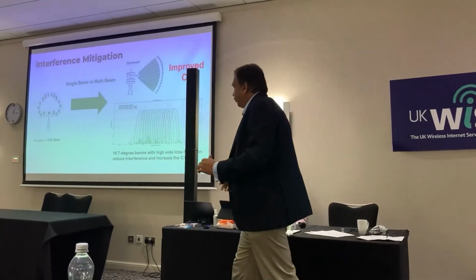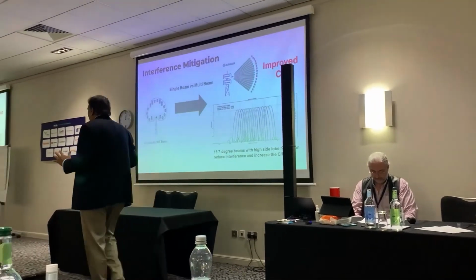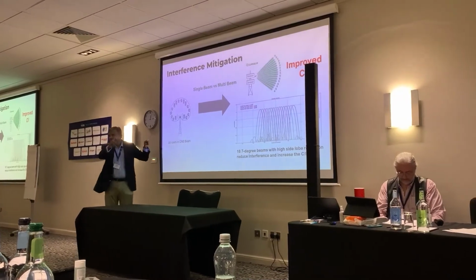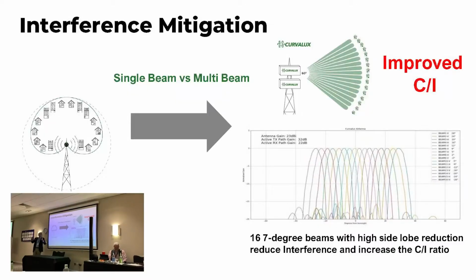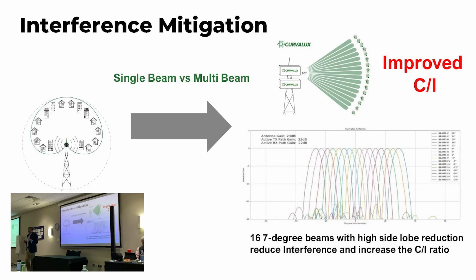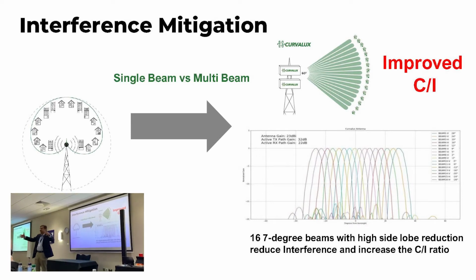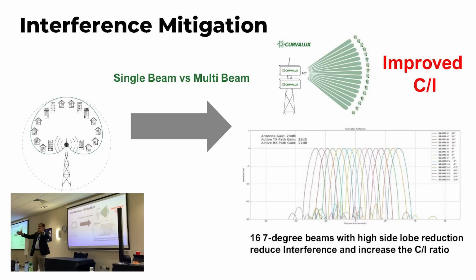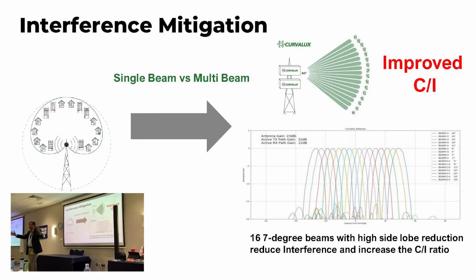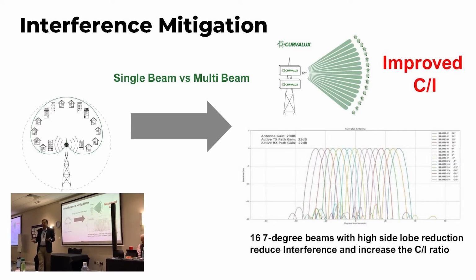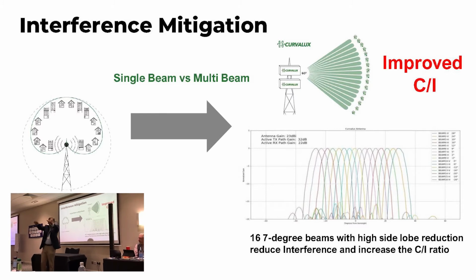Okay. So far, if you see what is going on, what are people putting? People are just putting either the omnidirectional antenna, radiating in all directions, gain 9 dBi, 10 dBi, 11 dBi. And if you ask why you are getting more range from the omnidirectional, people say that we have increased the gain, or our pattern is more omnidirectional, which means when you move in a circle, the power doesn't fluctuate that much. As an antenna designer, if somebody asks me what is the best omnidirectional you have designed, I will just say higher gain and no ripples.